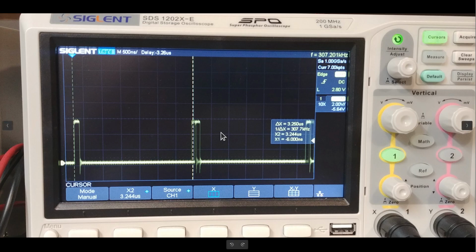In other words, the SIO is going to use the leading edge on these clocks to determine when to do its internal state machine processing to handle the data transfer on its serial lines. Other UARTs might require a 50% duty cycle wave. They may, in other words, use both edges of the clock. All right, so be careful what you use. Read your data sheets. Always know what's going on.